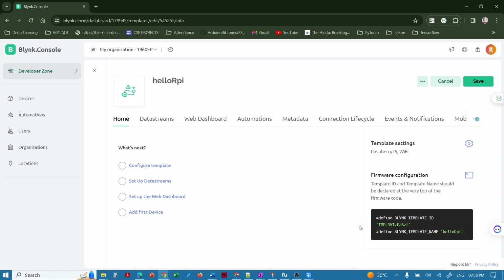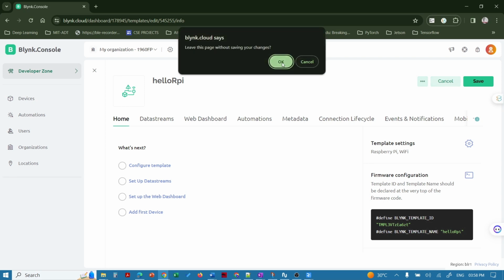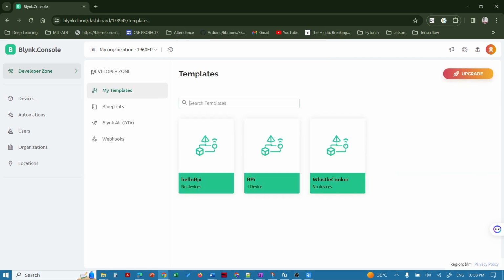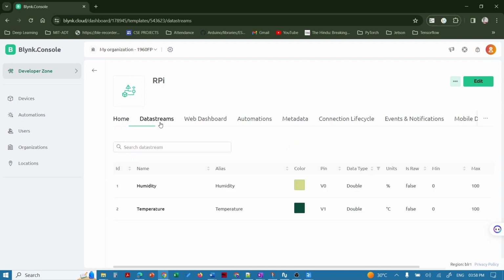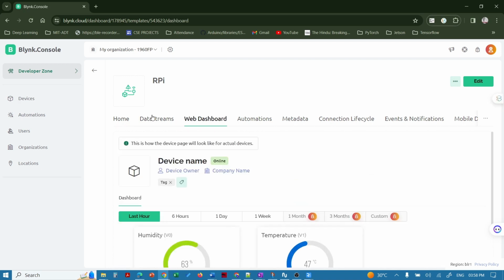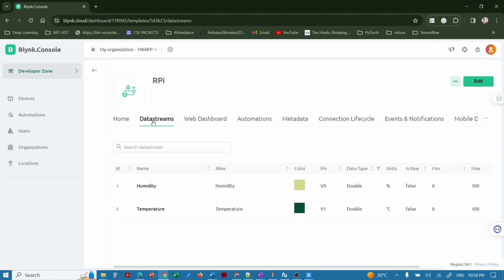Whenever you want to pass data from your Raspberry Pi to this Blynk console, we are accessing the data via virtual fields, virtual entities. So V0, V1, V2 are the pin numbers in virtual form. I want to show the temperature and humidity values over here in the virtual field, so I access those using a new data stream as a virtual pin. Click on that as a virtual pin, give the name,